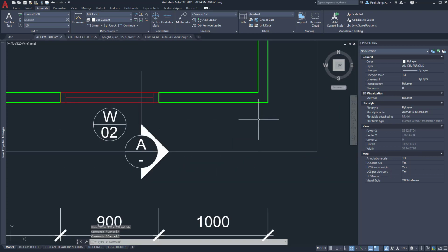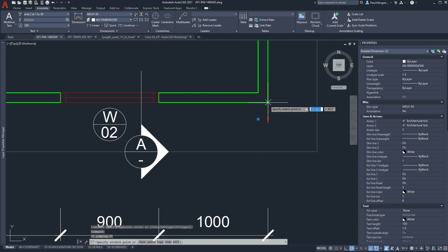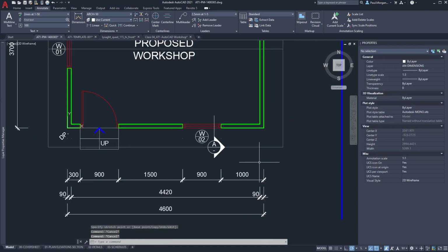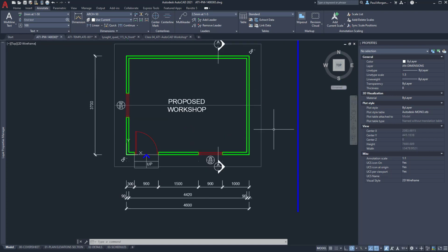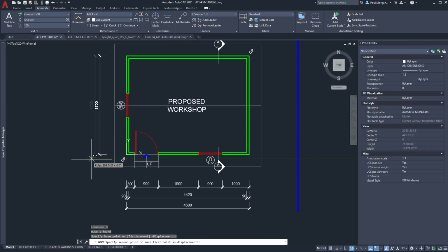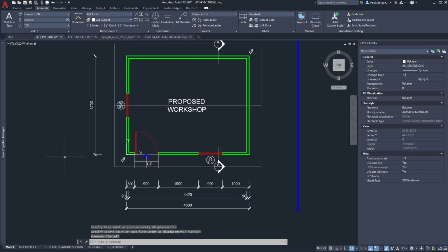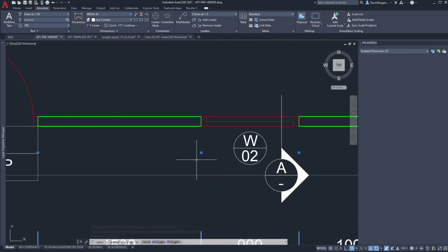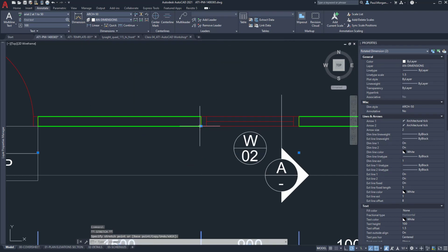You will notice that there's these tiny little dots on the screen. Those tiny little dots that you're seeing are the references of where I took the dimensions from. And annoyingly, you have to sort of move them back if you were to do that. This is why sometimes redimensioning them can be quicker. Or my tip for you is dimension further back than you actually want, because it's generally easier to move a dimension closer and you won't see those dots. But if I move them further out, you can see those dots appearing on the left-hand side. So generally, I dimension further away, move the dimensions inboard rather than doing the opposite. Otherwise, you'll be left with these annoying white specks everywhere that you've got to go moving back into place.